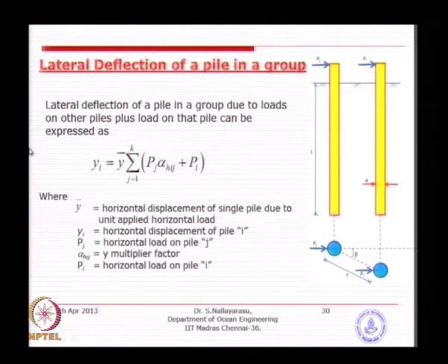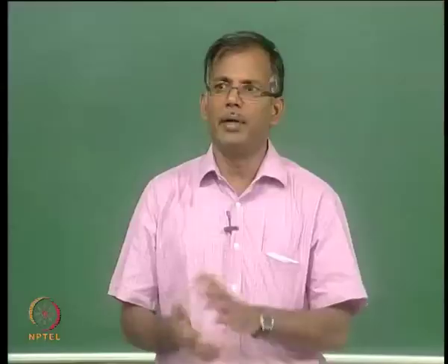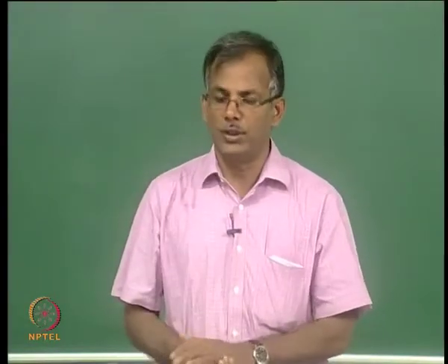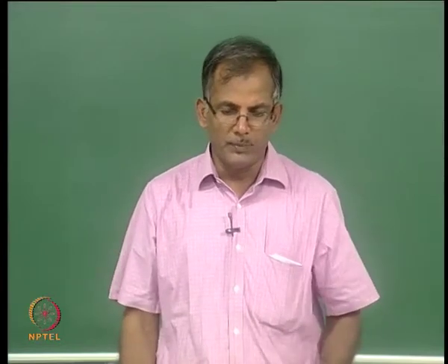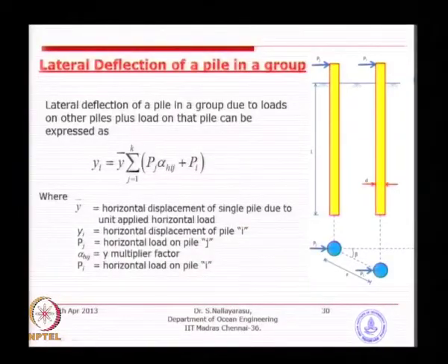So, as I mentioned for the vertical pile, you can see here is a cumulative effect of a particular pile displacement because of the loads on the neighboring piles. So, you could add from 1 to n number of piles. It is a generalized procedure given in a textbook, which we generally use in practice, basically Joseph Bowles' book. It is based on a simple matrix methodology. In fact, you might have studied in your structural analysis program the matrix method of solution, by dividing the pile into several subsegments and solving for the displacement along the full length. Once you find that, you just iterate for all other groups.